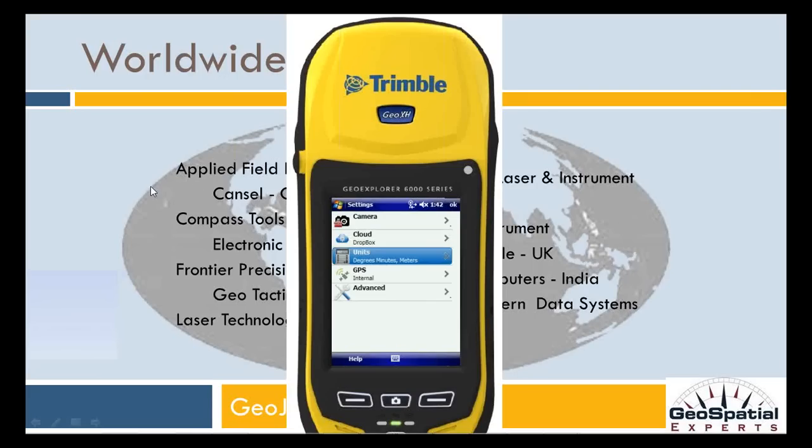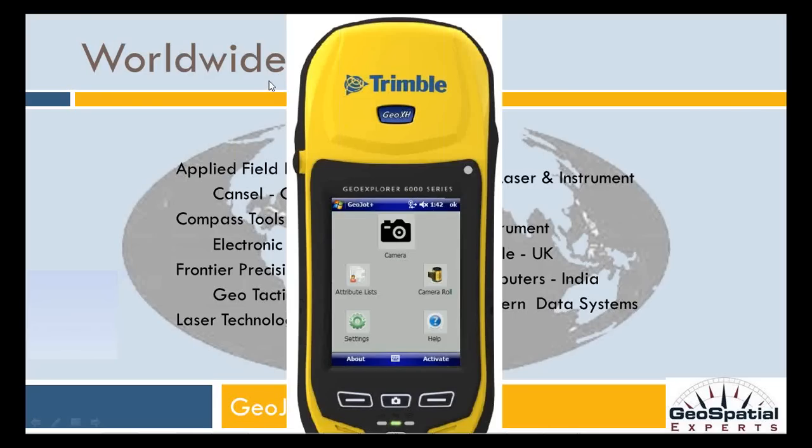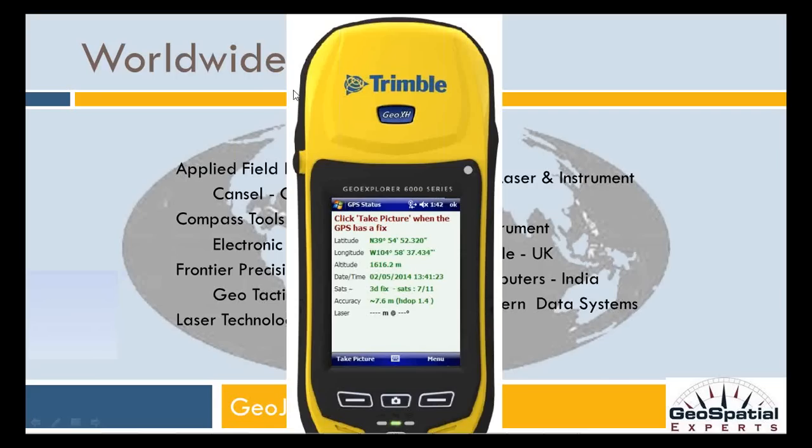Okay. I see a question from Dave Rios asking, does GeoJot display the accuracy anywhere? And the answer is, yeah, if you look here on the screen, the bottom setting right above the laser setting here on the device will show you what the accuracy is. The accuracy estimate is based on what the accuracy numbers that the device is feeding it. Now, we're inside a building and fairly centralized, so obviously it's saying 9.7 to 7.5 meters. So the accuracy is going to be much better when you're out in an optimal environment. Just like with any GPS device, optimal environment equals the best accuracy. But GeoJot does display the accuracy there, so you do have an idea of the accuracy you're getting before you capture that photo.